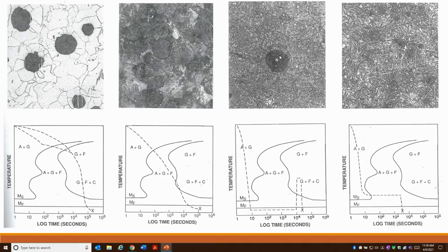But with ductile iron and any of these microstructures, you're going to be measuring your nodularity and your nodule count. So your nodularity is how round those nodules are, and that gives you an idea of the quality of the ductile iron. And then you will also do a nodule count. Your nodule count's based on your inoculation that happens after your magnesium treatment. The more inoculation that you have, typically the higher the nodule count. But overall, the higher the nodule count, and the better the nodularity, so the more round the nodules are, the quality of the ductile iron is typically better when those are higher.